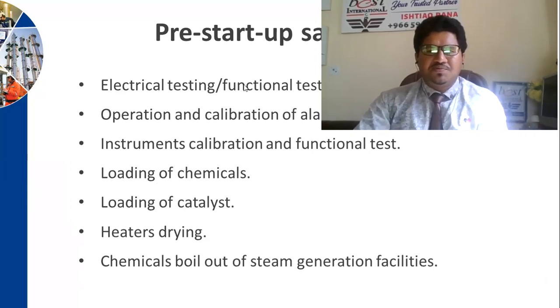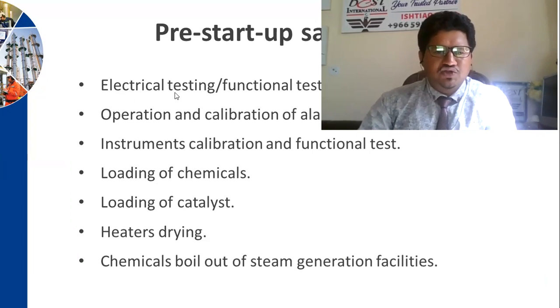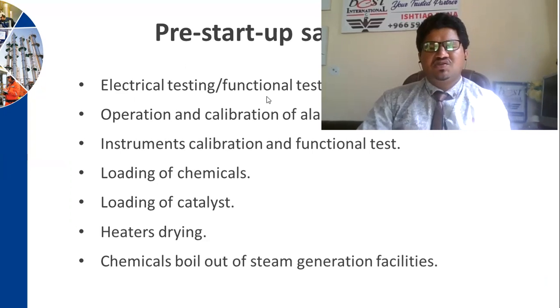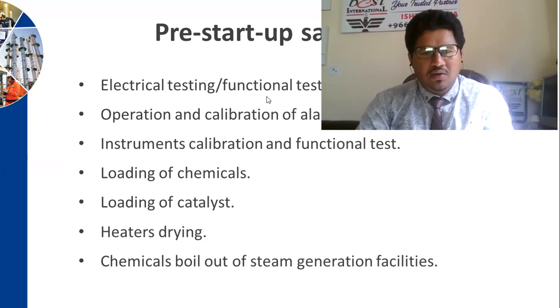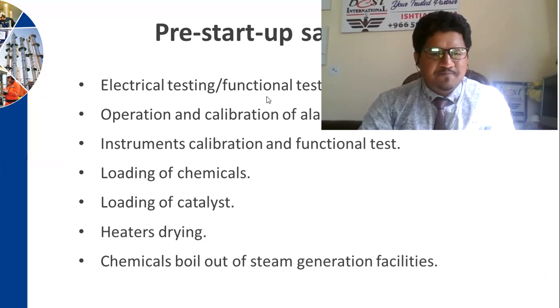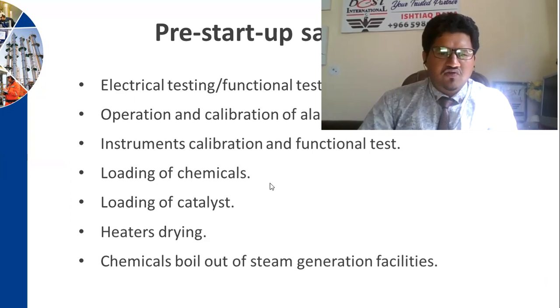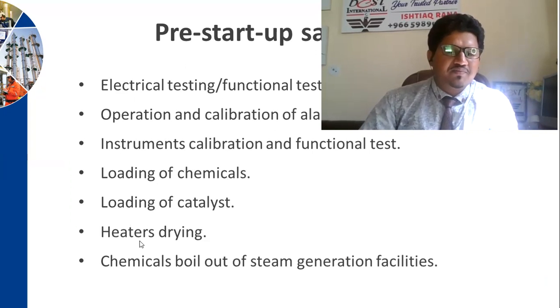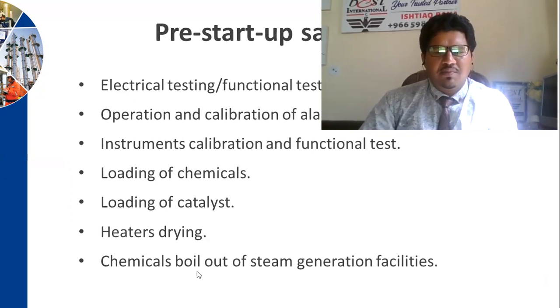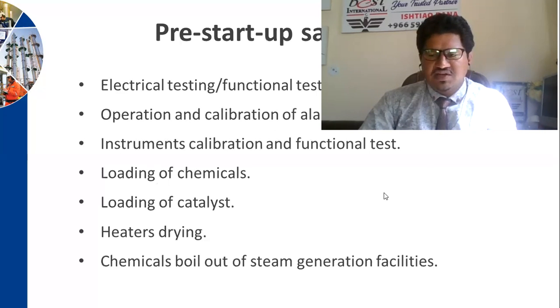Pre-startup safety review still requires more points to be considered, like electrical testing, functional testing, energizing, operation and calibration of alarms and relief valves, instrument calibration and functional tests, loading of chemicals, loading of catalyst, heater drying, and even chemicals boil-out of steam generation facilities.